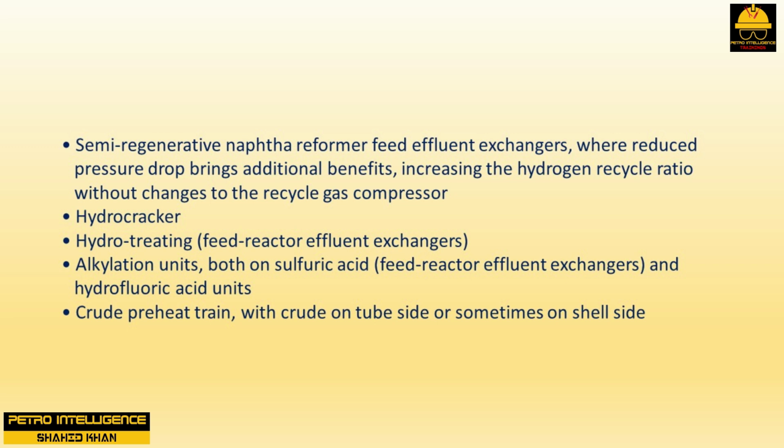Hydrocracker, hydrotreating, feed reactor effluent exchangers. Alkylation units, both on sulfuric acid, feed reactor effluent exchangers, and hydrofluoric acid units. Crude preheat train, with crude on tube side or sometimes on shell side.